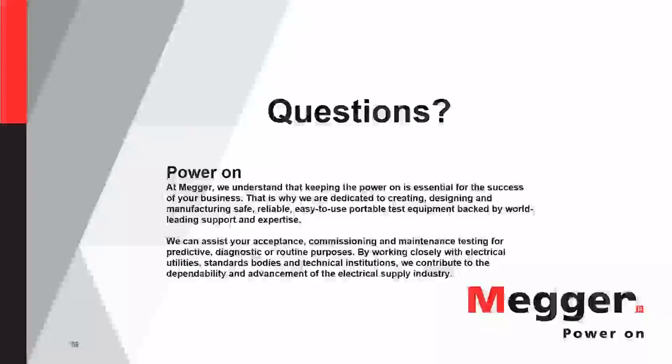Okay. All right. Another question was from Jonathan. He asked, should the transducer be calibrated on a certain interval? And if so, what is the recommended interval? So this is the same thing that we kind of previously answered. There's not like a standard one. If you're really worried about it, our standard is once a year or so. Like if I was a manufacturer and you're pumping out 10,000 breakers a year, you're operating that transducer a lot, so they're probably going to calibrate once a year.